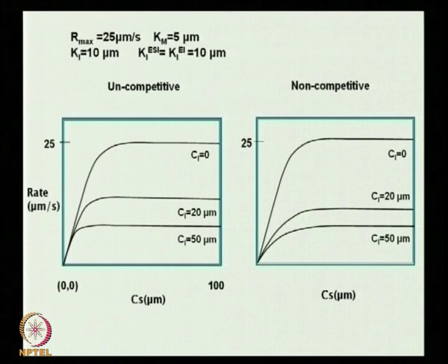So, even if you are taking it out at a constant rate, say in a CSTR, what is the problem? The problem is the product gets to spend a fair amount of time in the reactor, right? As a result, it will still be inhibited. So, yes, taking the product out continuously is a theoretically correct answer, but it is not a practically correct answer, because if you are using a CSTR, it has a certain residence time and you cannot do anything beyond it, right.